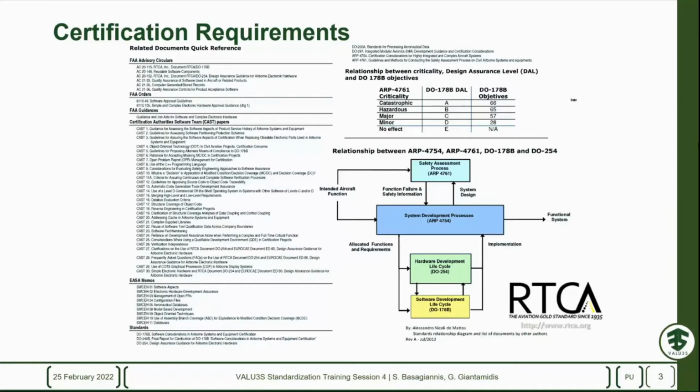But not all of the requirements, you understand, have the same priority. On our side, we have DAL A until DAL E criticality for those requirements, starting from the most serious, which is DAL A. You can consider that the control that we are placing on the FADEC, which is the fuel authority digital control device that is controlling the engine of the aircraft, has to pass a DAL A certification, and then we go down to DAL B, C, and D, where the DOs don't have much application to those.